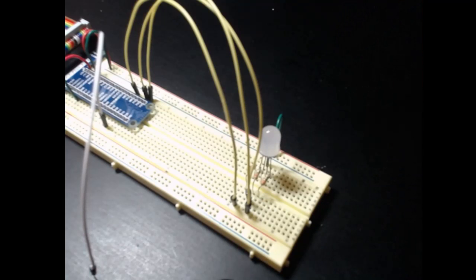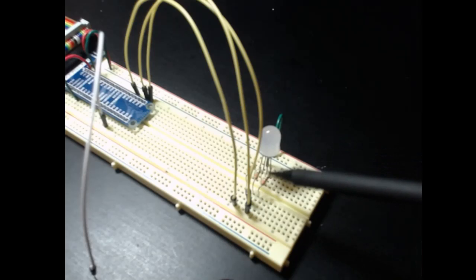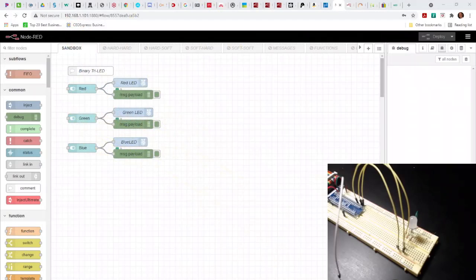So we've hooked up this LED in the same fashion that we did with the individual LEDs, but we've connected the common cathode to ground, and we have our 3 current limiting resistors in here in line. So let's now switch back to the dual mode, and you can see what we've got here now is the same connection as we had before with the individual LEDs, but they're just wired all together.